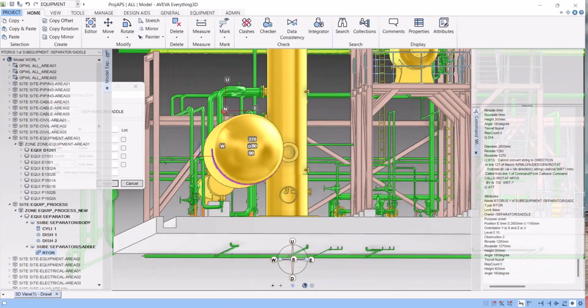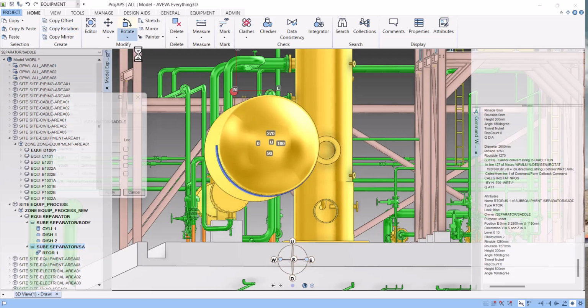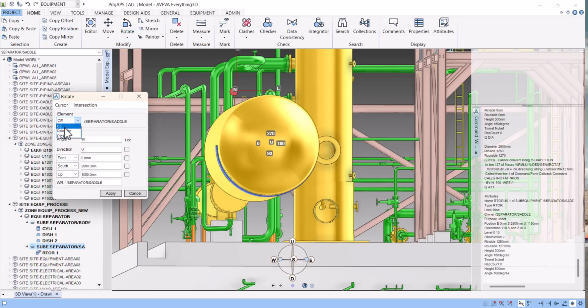You have to rotate the torus again, advance. See here, and then select element this one. And now you have to click on south because I want south. And my angle should be 5.